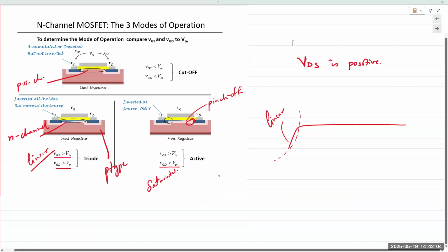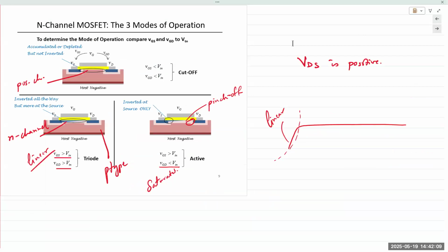The three terminals are known as the gate, the source, and the drain. The drain and the source are the two N-type regions. The gate is the controlling terminal. Current flows between the drain and the source. So similar to a BJT, you have a three-terminal device. Current is flowing between two terminals, and a third terminal is used to control the flow of current.